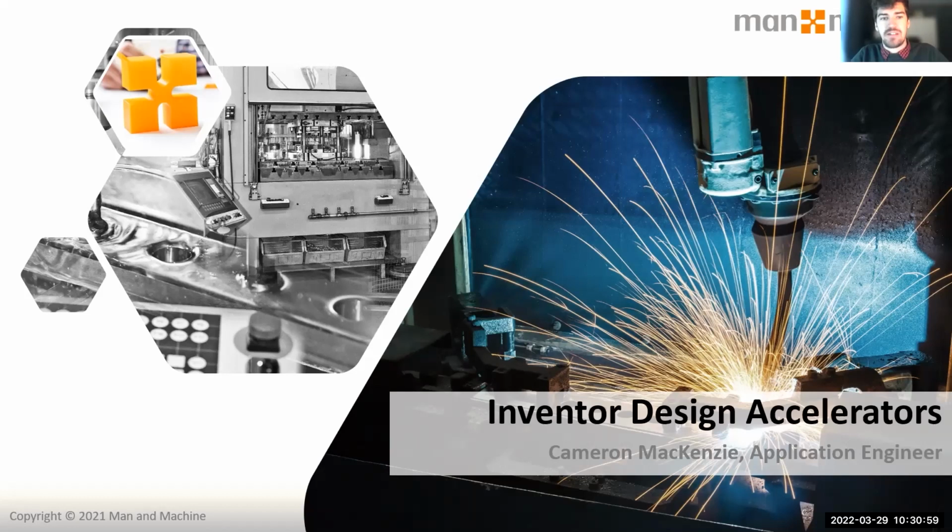What the design accelerators will do is take certain standard parts, whether they be bolted connections, frame generation, bearings and gears, and use the Content Center that's built inside of Inventor to start to configure and help you create assemblies a little bit quicker. Again, building on the backbone of the Inventor Content Center.